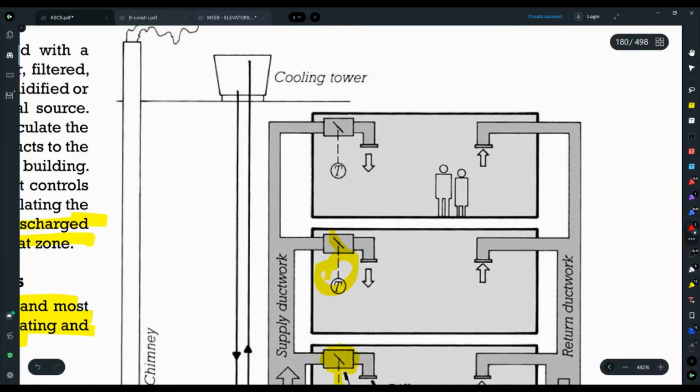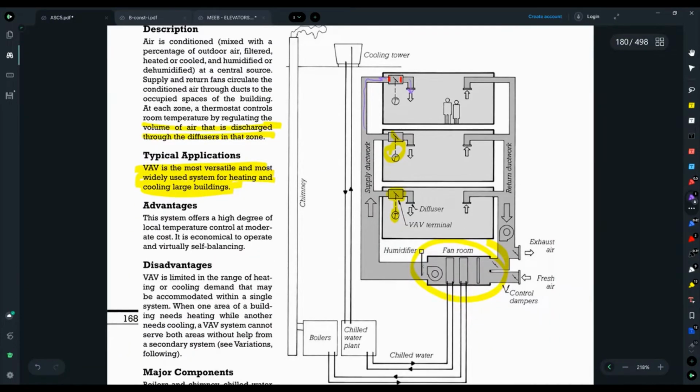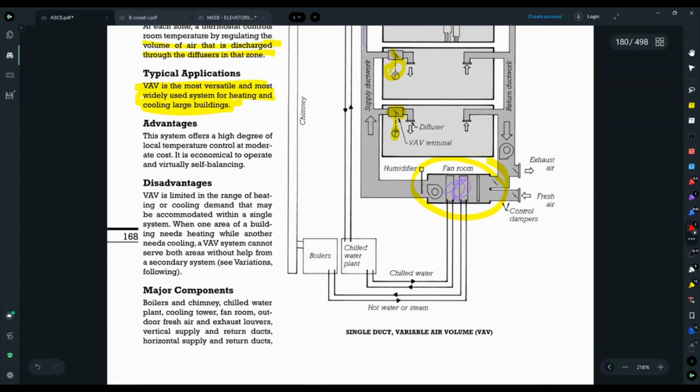So that's just the same system that we've just been looking at, except here, there might be a heating coil. Maybe it's electric, maybe it's a refrigerant pipe that just creates a hot coil here, and the cold air coming through here hits the heating element, and then you have slightly warmer air or much warmer air coming out into the space. Now, it's technically quite inefficient to be doing that, right? If you have cool air coming here and then you're just cooling air in order to heat it up again, it's obvious that that's really not that efficient.